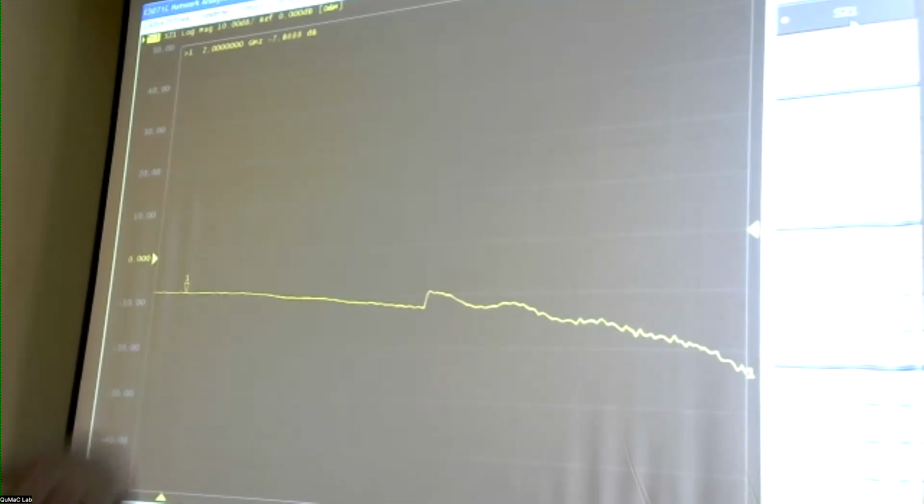And what does that standard measurement mean? It's by using these standards whose reflection coefficients are stored inside the machine. So you enter a model number for that particular thing. And open ideally should give you a reflection coefficient of +1 at all frequencies, but there is no such thing in reality. So it will be close to +1. But it will be a measured quantity and you feed that into the system. Similarly, the short will be close to -1 and the load, the 50 ohm matched load, will be close to 0 reflection coefficient.